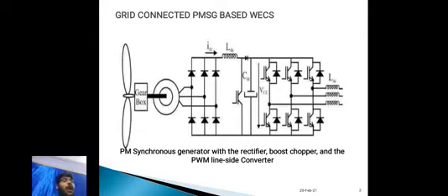By using MOSFET in the output stage, PWM technology makes the inverter ideal for all types of load. IGBT has high efficiency, fast switching, high current carrying capability, and is gate controlled using voltage instead of current. By using these, the active power and reactive power can be maintained.